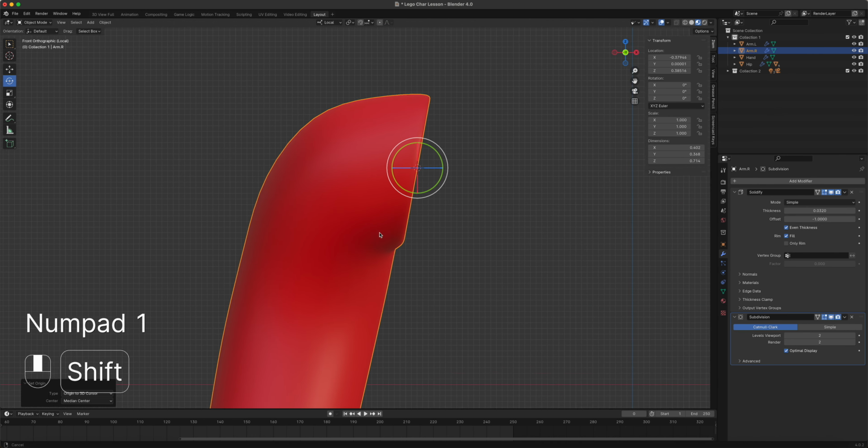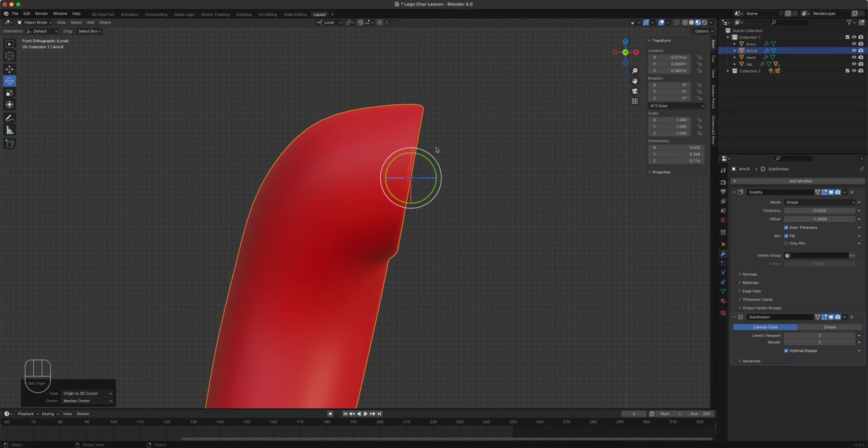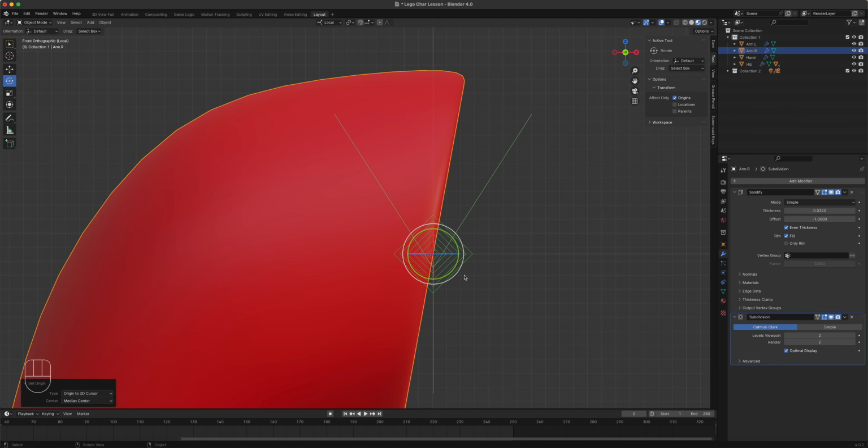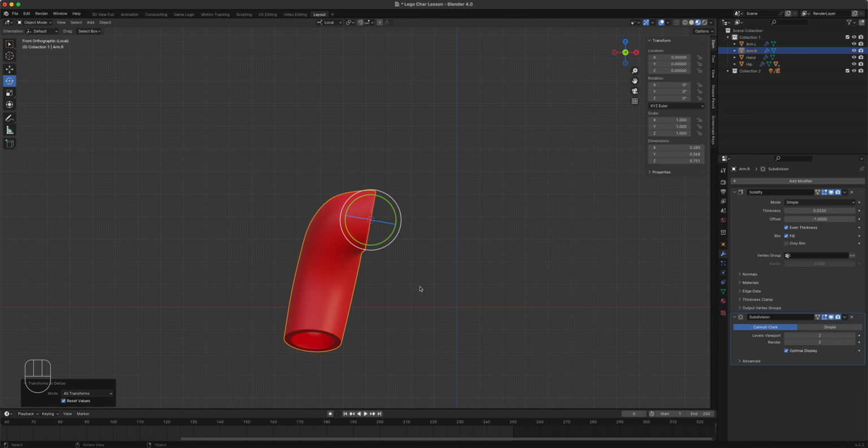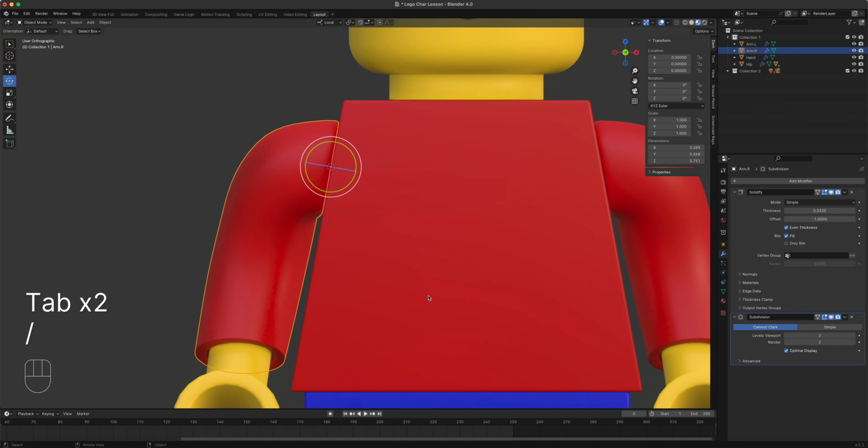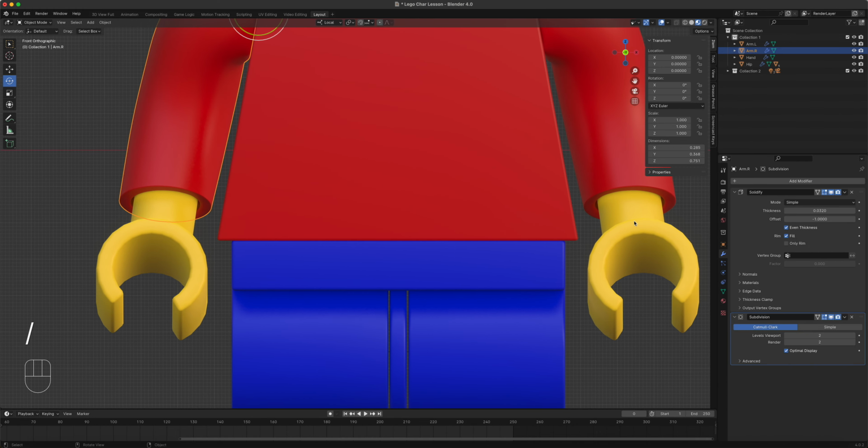But even on local, it doesn't know the orientation. So we're going to go to view, tool, Affect Origin. Then zoom in right here. I'm going to rotate this so it's aligned to that slant right there. Uncheck, and voila, we're here, and it's going to have values. So we're going to apply transform deltas, so everything is zeroed out except for the scale, and we are good to go there.